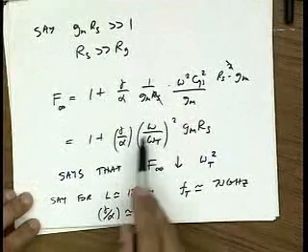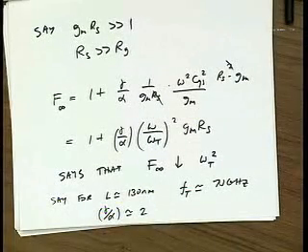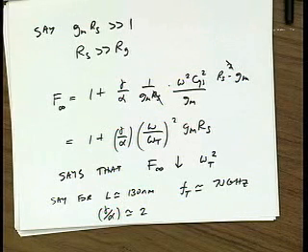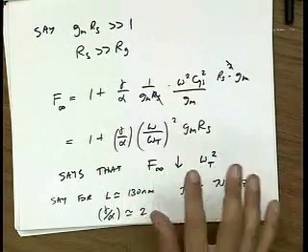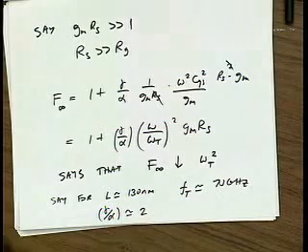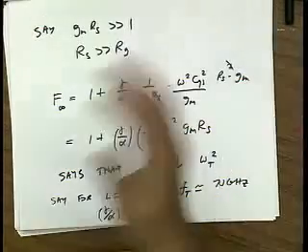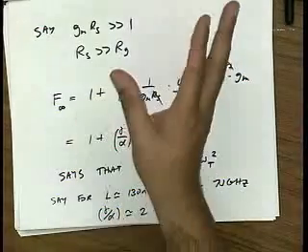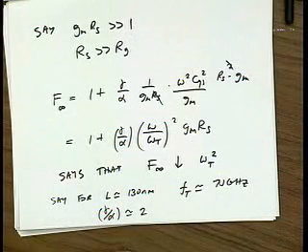And so you can see that if you're operating at a gigahertz or so, you can have a really low noise figure device. Now let me just recap these calculations with what we did earlier. We did not use the equivalent current noise and voltage noise at the input and all that theory. We just simply calculated the total output noise, noted how much of it comes from RS, took a ratio, and that gave us the noise figure.